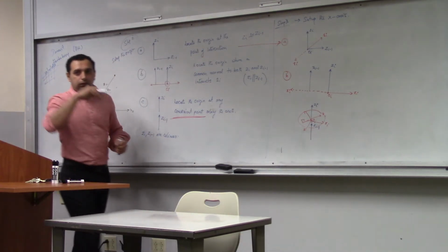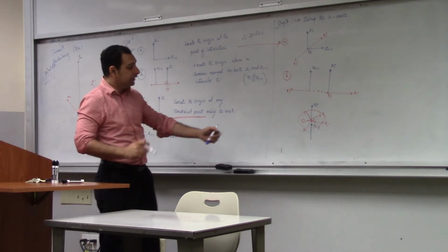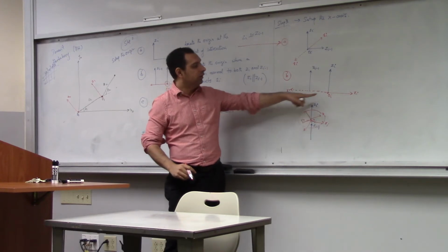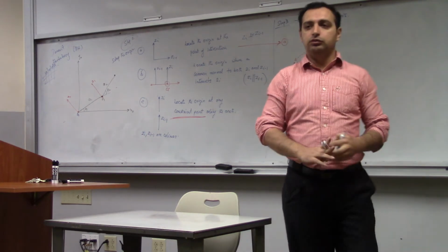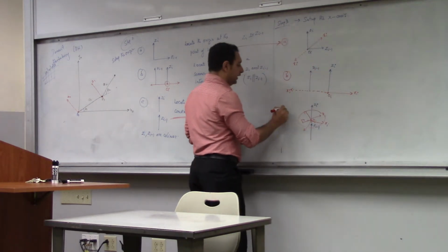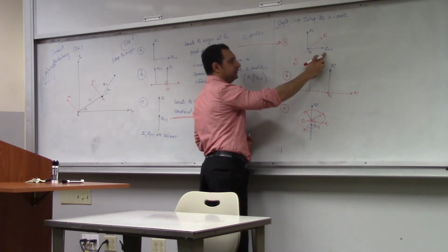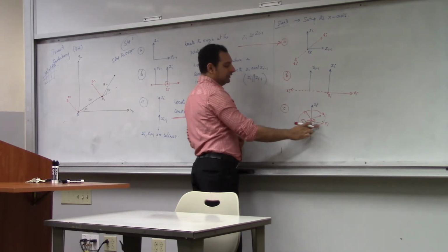But it has to be on Zi. It has to be through the origin. The origin is already lying on that axis. So it has to intersect Zi minus 1 and be perpendicular to both Zi and Zi minus 1. If you look at all of the cases, does xi intersect Zi minus 1? Yes, it intersects Zi minus 1.